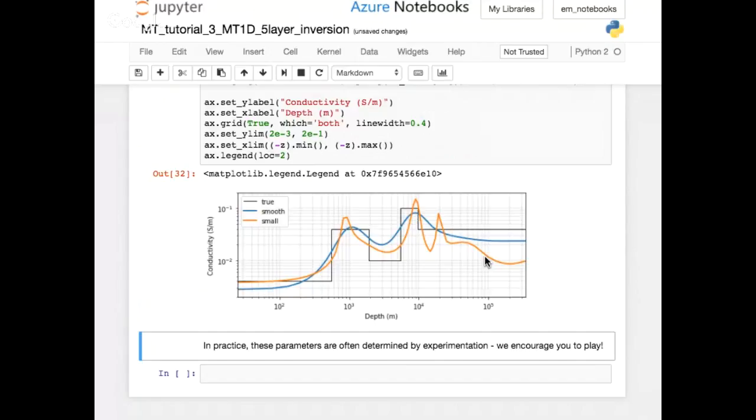If I make one comment here, that's actually a good way to address depth of investigation, which people are always worried about. One way of doing that is to change your reference model. You run it with 2 different reference models, then you look at the back end, and the smallest term will take it down to that reference model. When it does that, you know that you're controlled by your regularization, nothing with respect to the data. So that's at least one way of getting some sense of how deep your survey is.